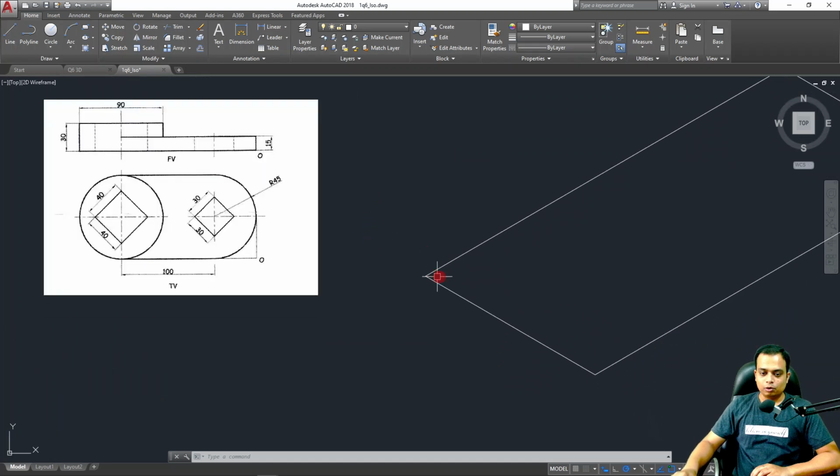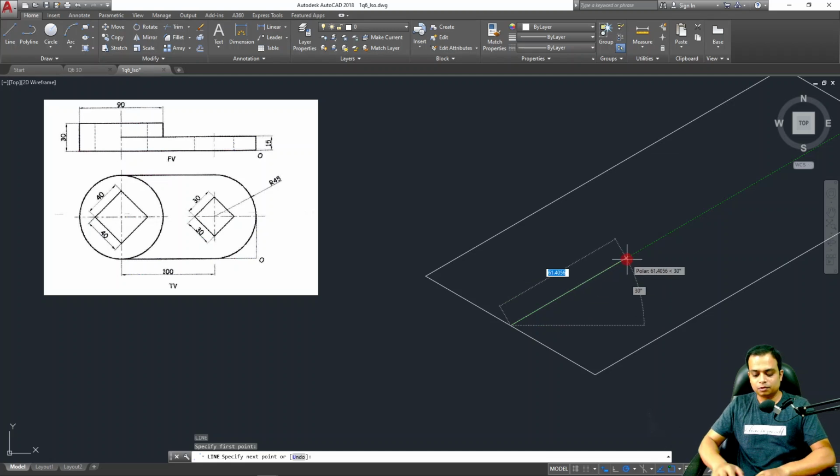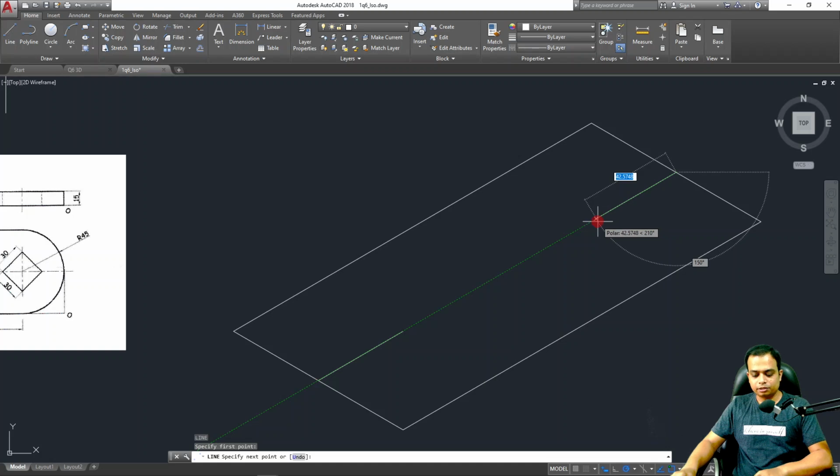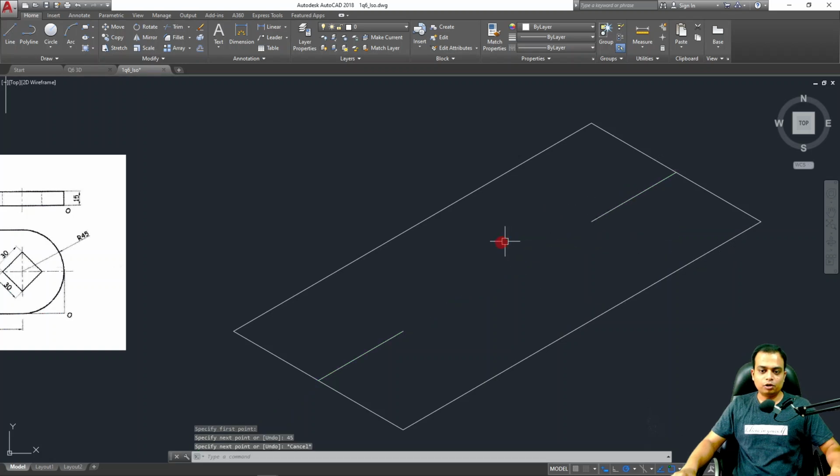What you can do is you can locate the center of this particular edge over here. This is where the center is. Okay, half of 90. Locate the center. And then move along this direction. How much? Sir, this is 45. Enter. Done? Okay, sir. Now, this distance also has to be 45. Again, locate the center. And in this direction, 45 and enter. Again, you've got the centers.